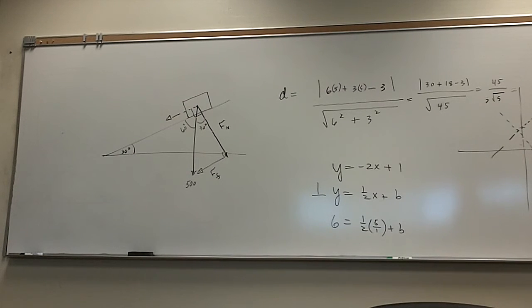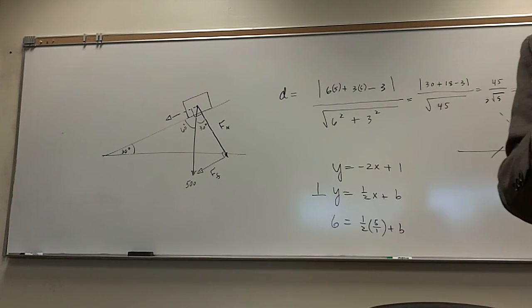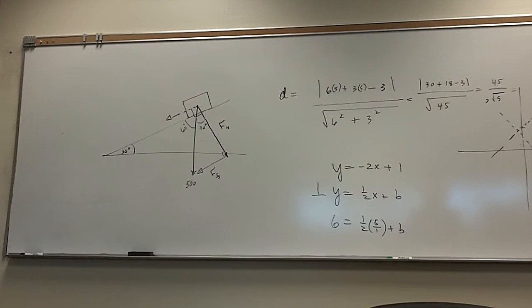And they have done this over and over and over again. They have calculated for you, and they put it in engineering books, coefficient of frictions. Wood on wood has a coefficient of friction of a given number. Teflon on Teflon has a given number. It's quite low, a very low number. Rubber on cement has a coefficient of friction. Rubber on asphalt has a coefficient of friction.